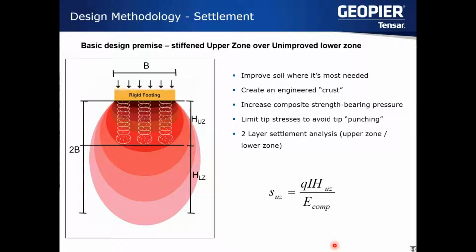So, like I mentioned, for building work particularly, settlement is almost always going to control. We're typically controlling the 1 inch total, half-inch differential. If there are tighter requirements, we just need to know that, and we have to design for that. But as we get into industrial structures as well, something else to think about is, we do see some yielding problems in some instances, and maybe even some bearing capacity issues. But often settlement is the driving criteria 99% of the time.